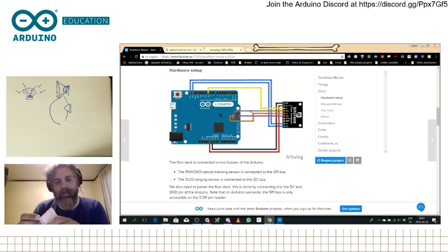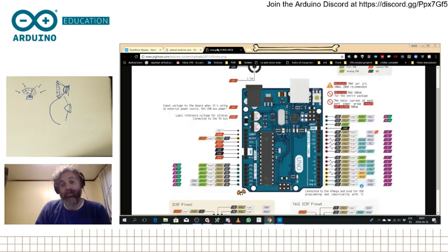Then one that is called CLK, which means clock. I will take green. And the next one is called MOSI. And for that one, I will take blue. And now I need to make sure that these pins are properly addressed on the Uno. And on the Uno, you see that clock is actually pin number 13.